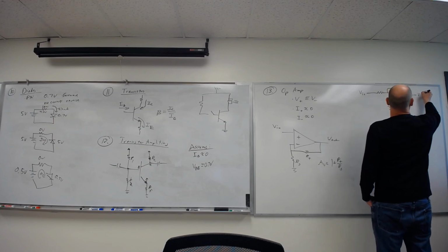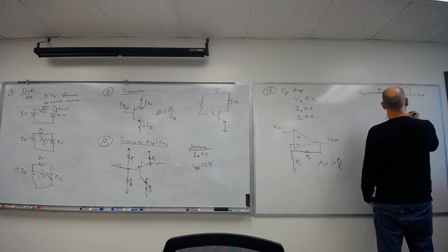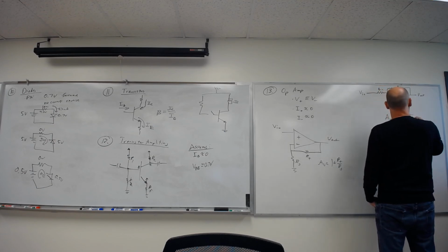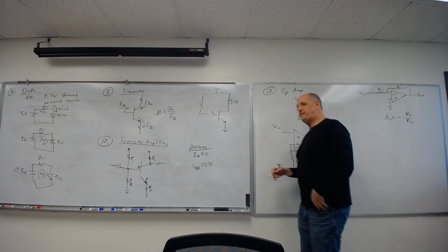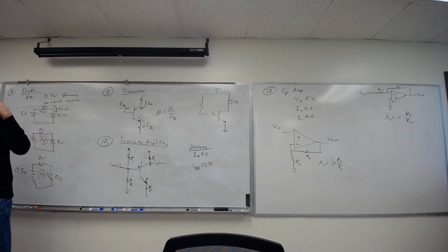This is the inverting op amp. Input resistance, feedback resistance, the gain on it was minus RF over RN. When you did the lab, you found out those gains were pretty much right on, right? I think in the lab you got minus 10 for the inverting, and you found out that until I start hitting the rails, my supply's not keeping up, I'm getting a gain of minus 10. And for the non-inverting, you got a gain of 11. You put in 0.1 volts, you get 1.1 out, exactly 11 times more.